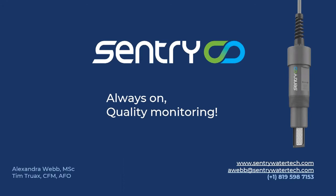I got a lot of good information from SENTRY initially about good locations, ways to secure the probe in the locations. Originally, I had the primary clarifier probe installed in between the scum baffle and the weir of the primary clarifier, but it's found that because of our particular wastewater, solids were accumulating on the probe, and I thought that may be interfering with the signal that was being generated.